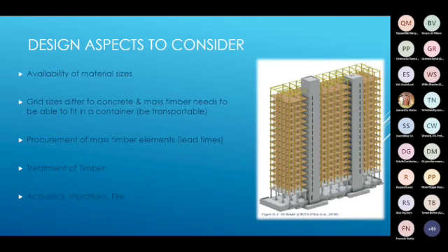Moving on to the treatment of timber, I conducted an interview with a SAWPA representative in my thesis to find out more about the treatment, as it has been quite a contentious topic for some time. SANS 1005, I think, specifies that timber used in the erection of buildings within the coastal zone of SA needs to be treated for termites and wood borers and fungal decay.